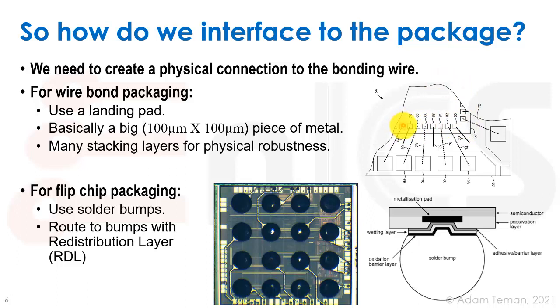And just because we're going to go wire bond, which means we're going to take this soldering needle kind of thing and land down on it and solder the wire bond to the pad, just for the mechanical strength over there and to lower the resistance, it's not just going to be in one metal layer. It's probably going to be like 4 or so metal layers with arrays of vias underneath. So just in case you break this very thin metal layer, then it won't cause some sort of open or something else, or a short inside the chip. It'll have some protection over there.